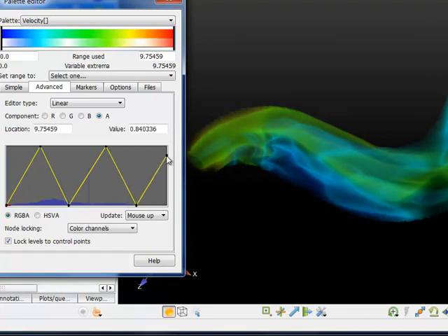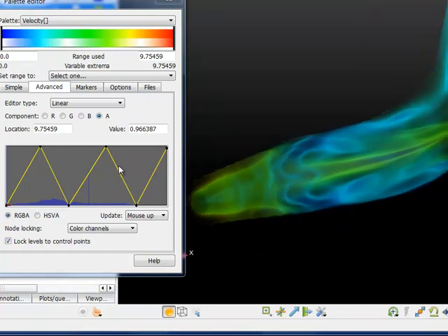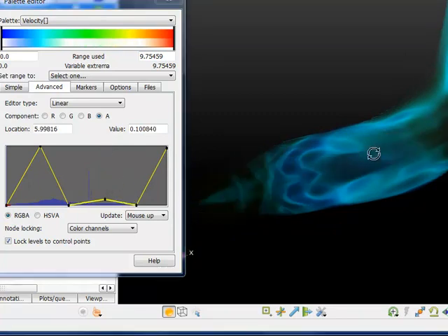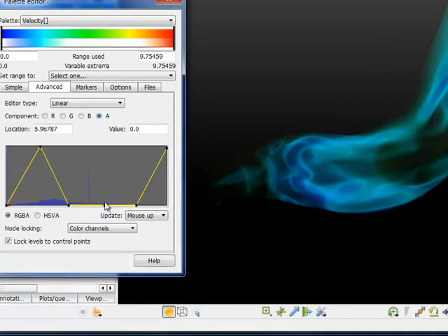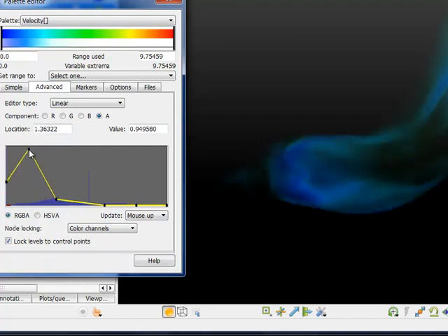And this is really the benefit of volume rendering, is that we can now render and look at a particular region of our model based off from velocity, but still be able to see everyone. So for example, let's not accentuate that region, and maybe really only want to look at the regions where we have kind of low velocity. So again, we can move these around a little bit and perhaps pick up an area which may be more important to us in this region here.